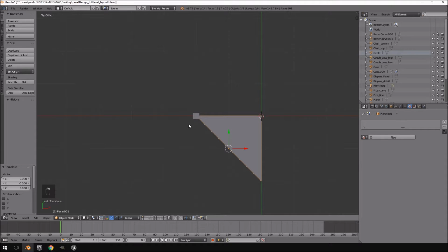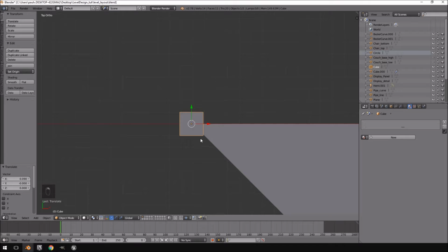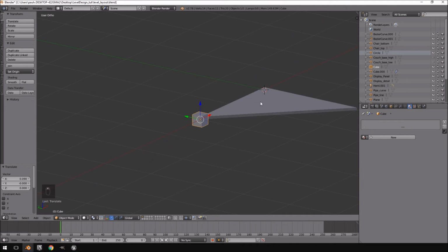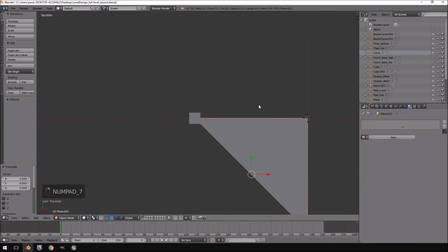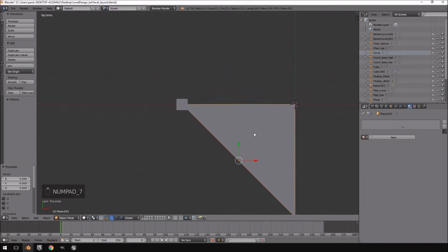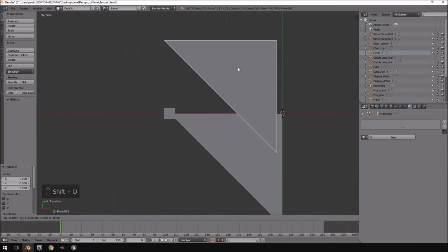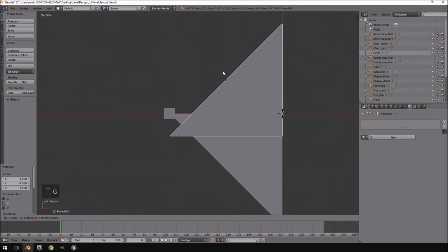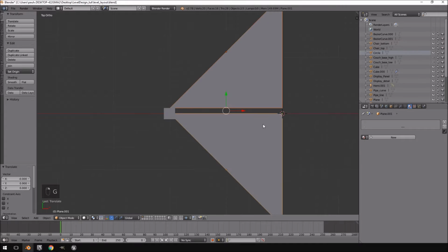Alright, essentially what we're going to do is create those strange little panels that they had underneath the floor panels themselves. The only way for us to really be able to see what that looks like would be to duplicate our mesh and then scale it on the negative y-axis by 1. And then grab it, and we're going to space it apart like a small grid unit.